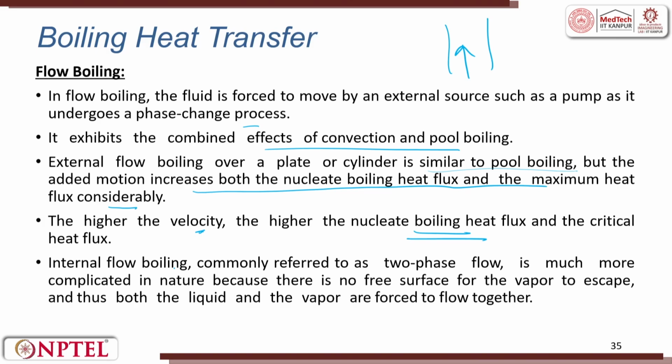Internal flow boiling is commonly known as two-phase flow. It is much more complicated in nature, because there is no free surface for the vapor to escape, and thus both liquid and vapor are forced to flow through the tube. So, this is called flow boiling.